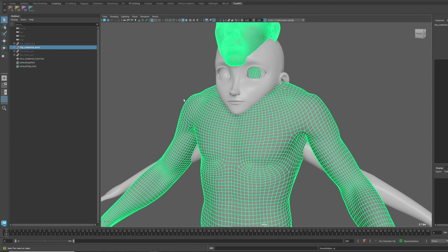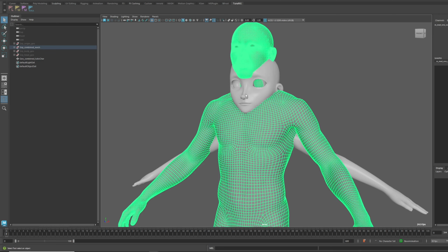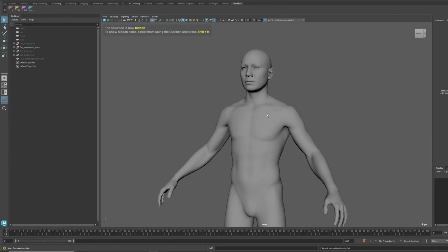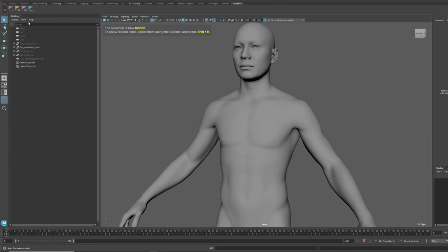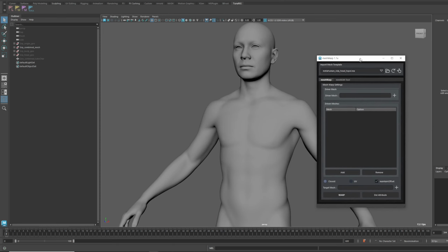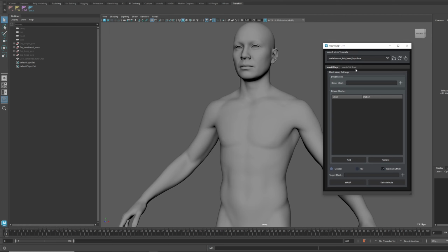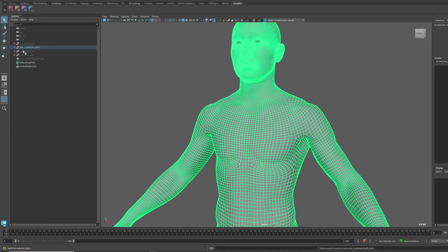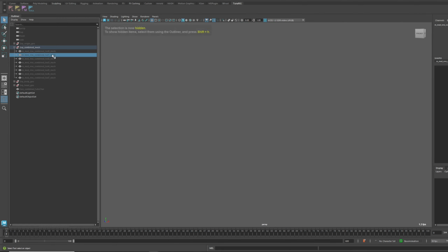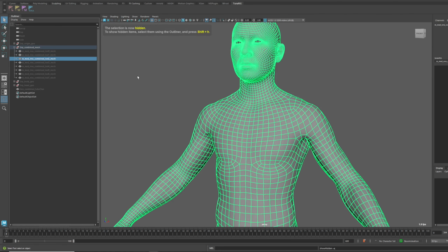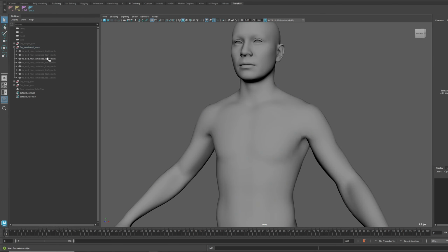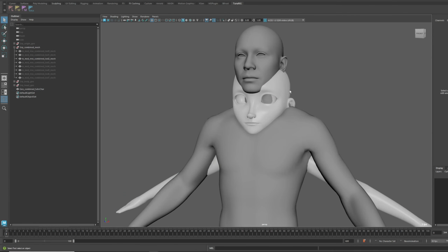Let's export the MetaHuman mesh as an OBJ file first. These MetaHuman meshes were imported as templates using the meshWarp tool from TunaTools. In this tool, you can freely load any template scene that you have set up. All right, now we are going to select a MetaHuman LOD that has a similar poly count to the original mesh. This step is crucial in the process of converting your original mesh into MetaHuman topology.